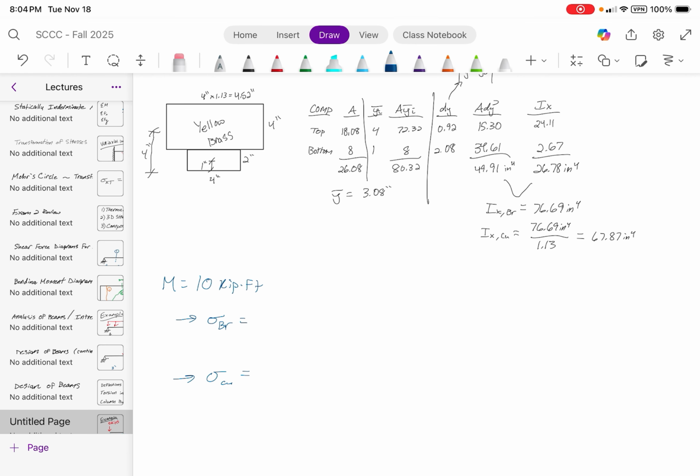Oh yeah, this is stuff I work on at work. That's a reinforcement shop drawing for a base slab, just a small part of the project. You have to count every last piece of rebar and make sure every piece is correct in there. You look at the drawing plans and make sure that the locations of all of the reinforcement are correct.